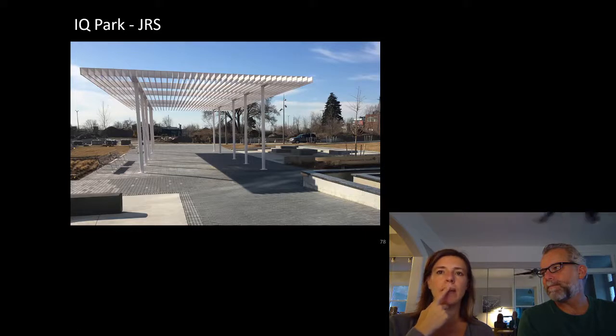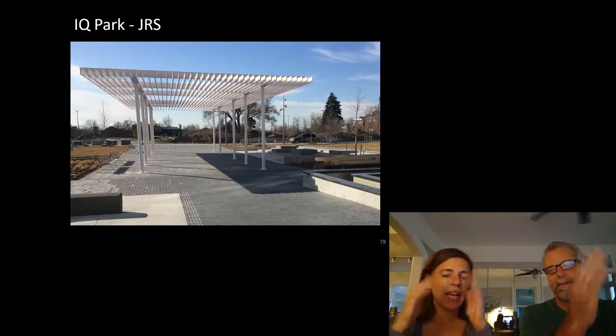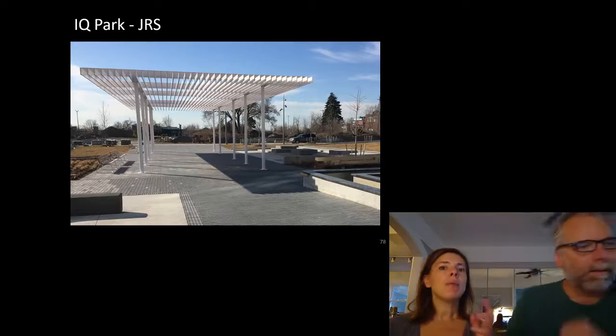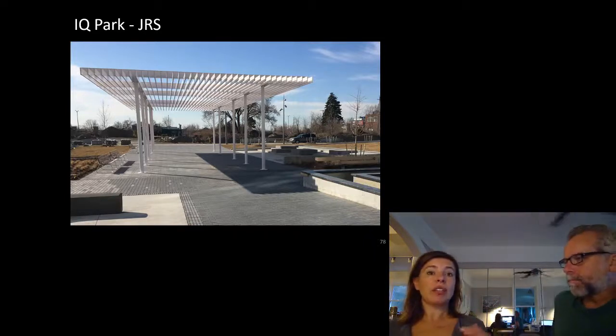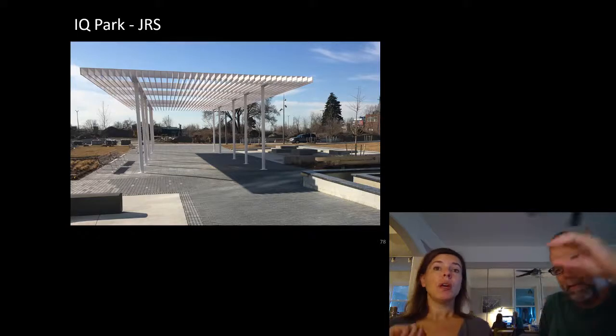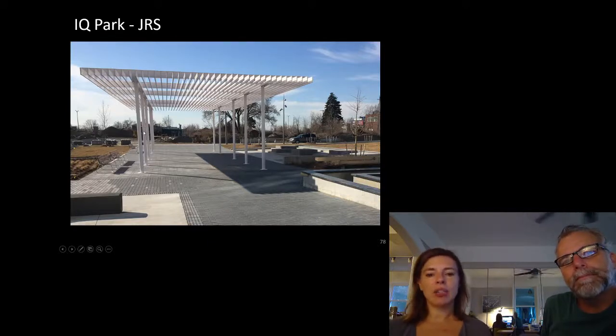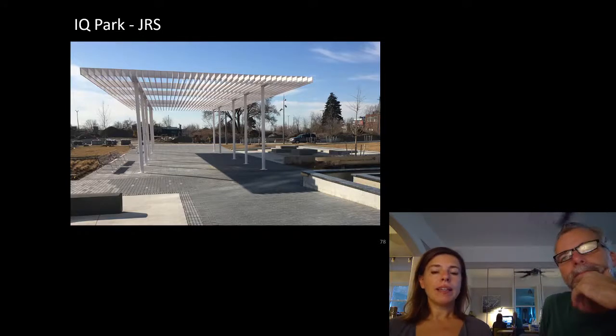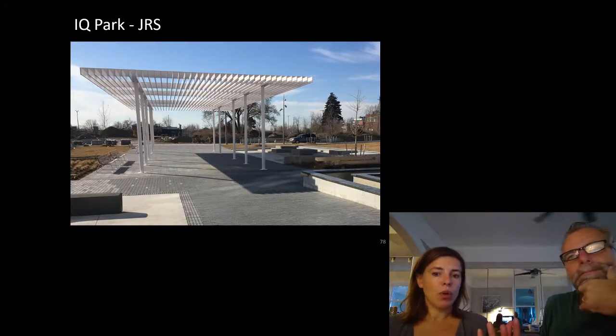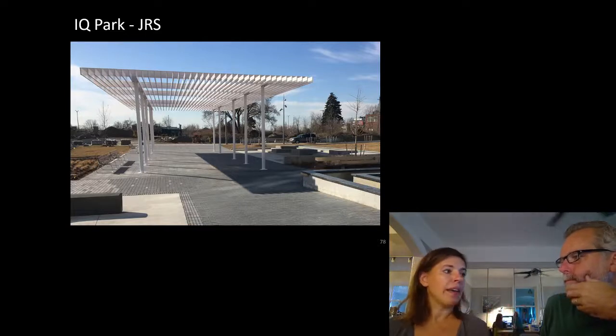You know what, now that I'm thinking about it, I think it might have been L/180 or even L/90. L/90, yeah, I was going to say, I'm using 1% as my drift criteria, cantilevering up. But I remember going through this one, and deflection was surprisingly not an issue, because the projected area is so small. I had moment frames in this direction and 5 cantilevers, or 10 cantilevers, in that direction, so the loads were very nominal. And even then, my loads were made up and quite high.